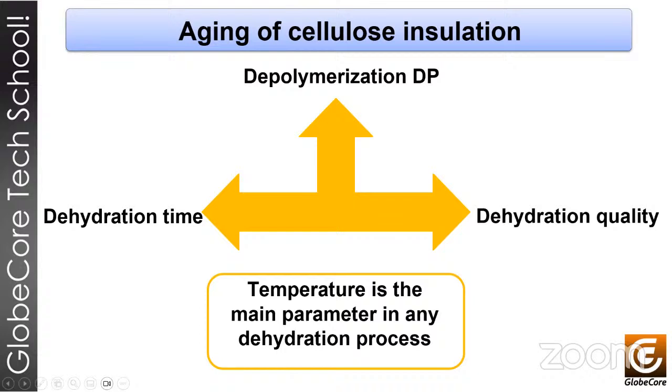To improve the condition of a transformer containing moisture, it should be dehydrated. These procedures are performed on site to minimize transformer downtime and to reduce process costs. To speed up the migration of water, the temperature of the paper must be high enough. However, it's very important not to exceed certain temperature limits, to avoid damaging the insulation. It becomes clear that the key parameter being controlled will be the temperature. Temperatures that are too high will damage the transformer, but temperatures that are too low slow down the dehydration process so much that it becomes ineffective.